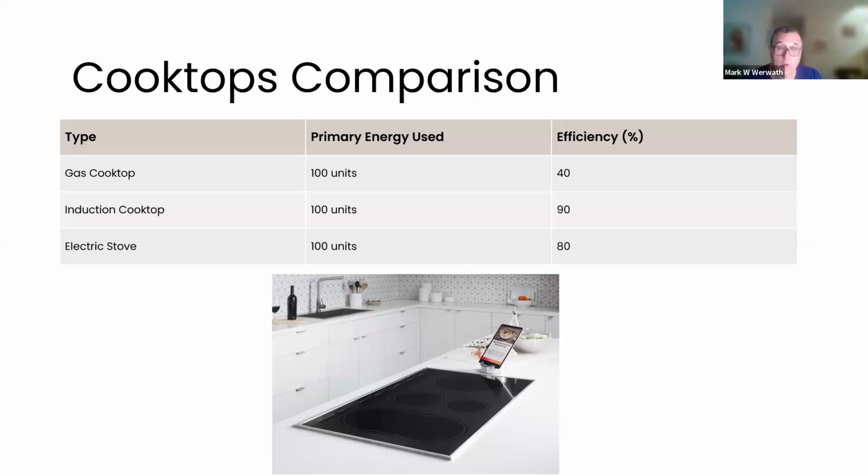What's the benefit of going induction? Well, besides the efficiency, which is noted here, you go from 40% efficient, meaning 60% rejected energy, to 90% efficient with an induction cooktop, right? It's safer. You can put your hand on it immediately after use because the surface is not hot. It transmits all the energy into the ferromagnetic pan that you're using, right?